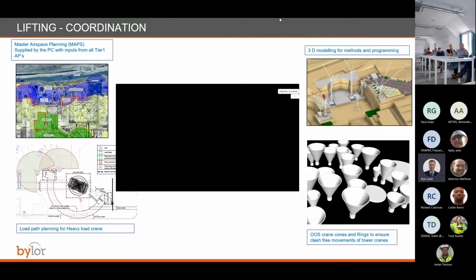So those elements, basically temporary works again, are tagged up to make sure that this is a loading area suitable for this bit of kit. I mean, not so much rebar and shutters, it's things like the MEWPs, the scissor lifts, things like that, that really take more attention because they're quite a lump in quite a small area with quite large point loadings.